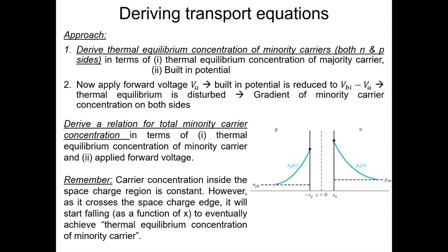So in the end, we need a current voltage relationship. We know the current flow in the diode is because of these excess minority carriers which are present in those regions, because the majority carriers in the neighboring region diffused into the other region, right? The diffusion process started because the forward bias was applied. So the built-in potential reduced and it further strengthens the diffusion process. As the diffusion process starts, you get these excess minority carriers, right? And these excess minority carriers, given they would have a certain gradient, would contribute to a diffusion kind of current, right?